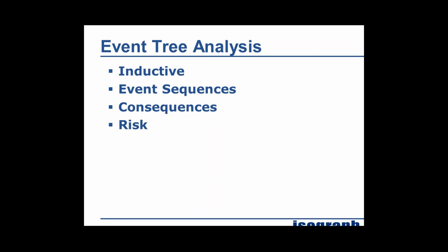And by risk is just a fairly simple concept. Risk is just how bad it is. It's usually calculated as the weighting times the frequency: how often does it occur, and how bad is the occurrence, which is the consequence. So event tree analysis can quantify risk.